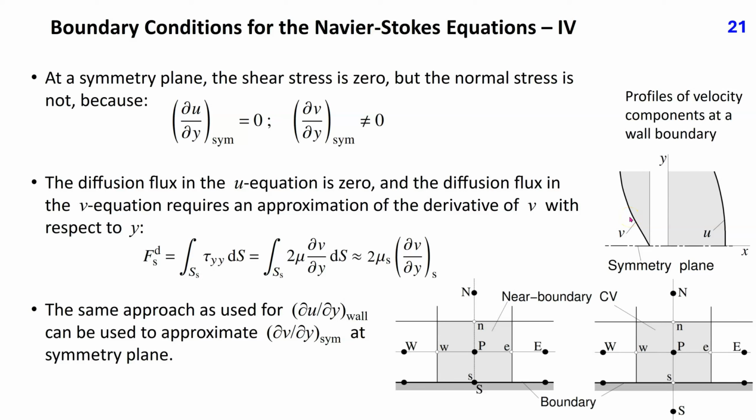If fluid decelerates along symmetry plane, for example, when approaching a stagnation point at an obstacle, the normal velocity component points away from symmetry plane. The opposite is true when fluid accelerates along symmetry plane. It then draws surrounding fluid toward the symmetry plane.